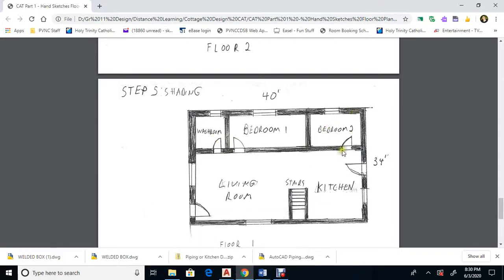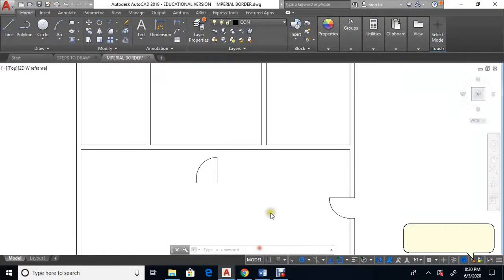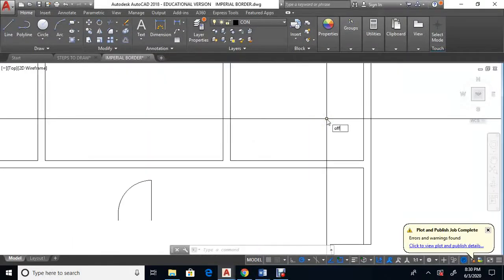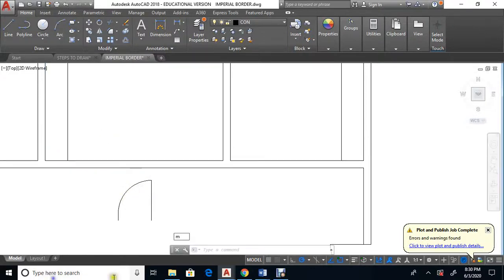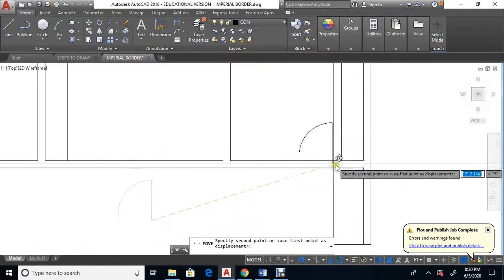So here it opens the same here, and I want about 2 foot away. So I'm just going to go over here, and I'm going to offset by 2 feet. Okay, I can do all this because I changed that to feet and inches. And I'll put another door here on this side by 2 foot. And I'm just going to move this door, or I can copy it, but I'll move this door. Okay, it opens and it's perfect from here to there.